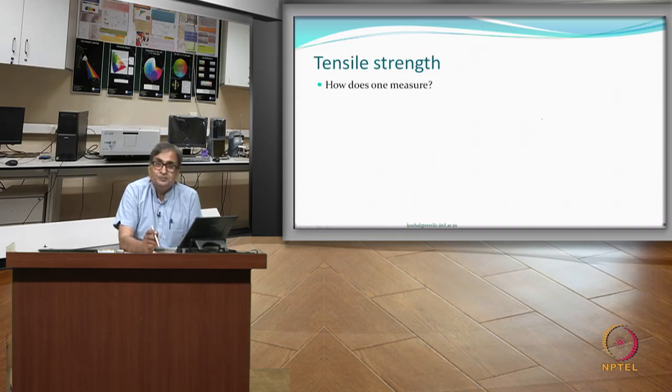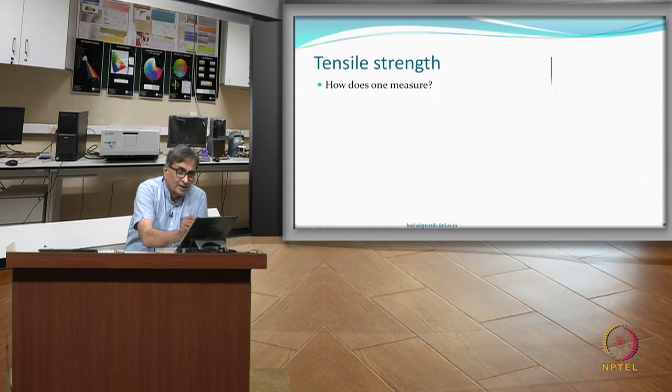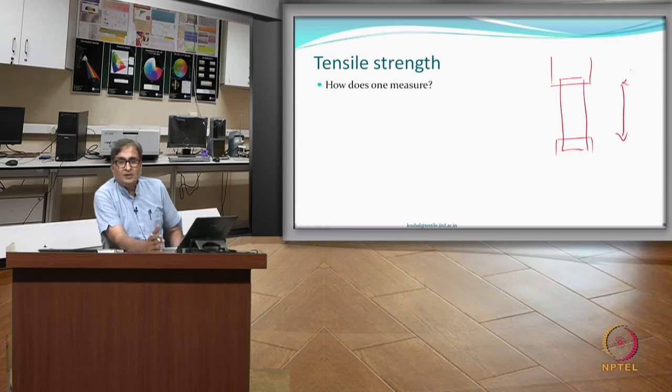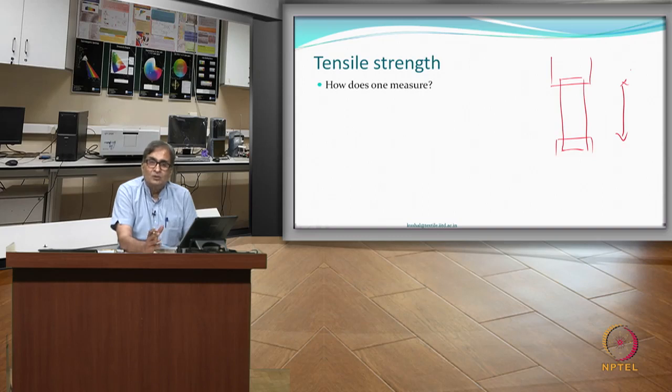What about tensile strength? How do we measure tensile strength? Well, you can have some tensile testing equipment which may have jaws. You can grip your fabric in the jaws and then increase the distance till it breaks, and then one can see and measure the tensile strength. The tensile strength of a fabric, a yarn or a fiber are measured in different ways which have been already defined. I am sure you would have gone through some procedure to measure the tensile strength of a fabric.